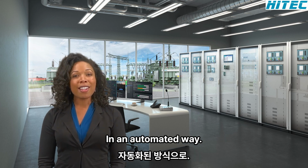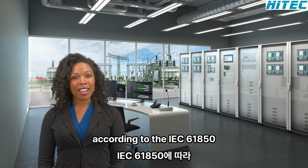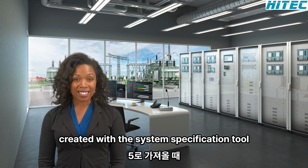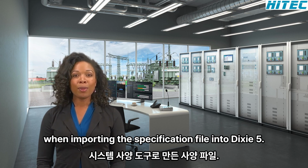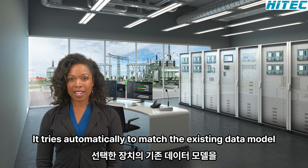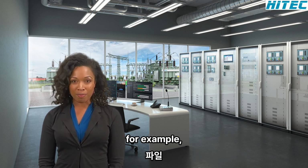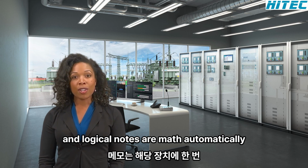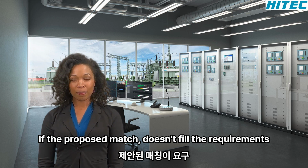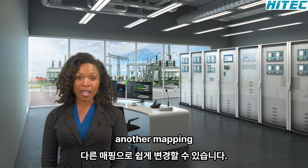DIGSI 5 supports you by creating the device data model according to the IEC 61850 system specification file created with the system specification tool. When importing the specification file into DIGSI 5, it tries automatically to match the existing data model in the chosen device with the data model specified in the file. For example, logical devices and logical nodes are mapped automatically to the correspondent ones in the device. If the proposed match doesn't fill the requirements, then it is possible to change them easily to another mapping.